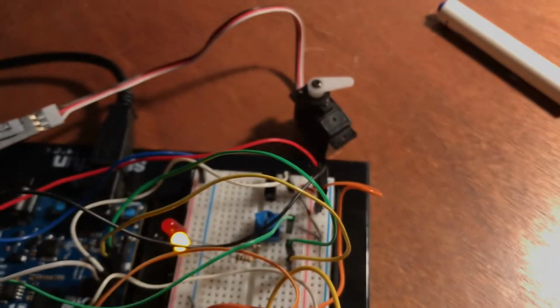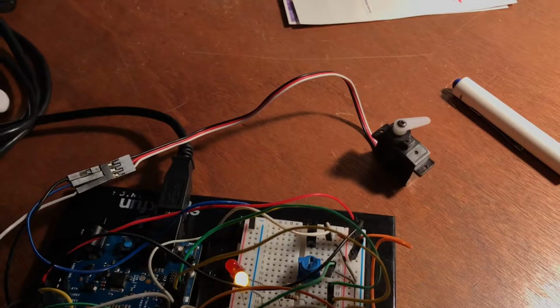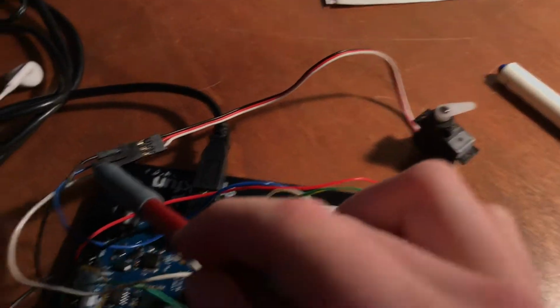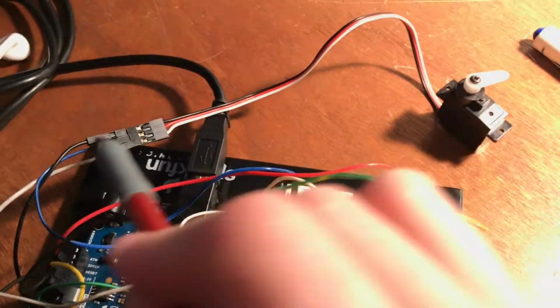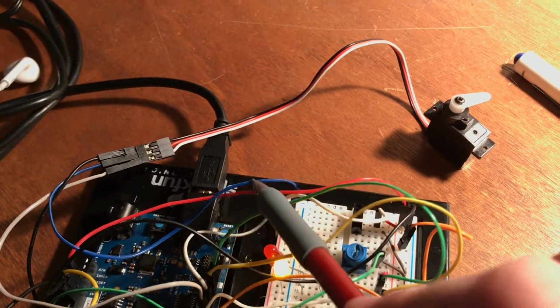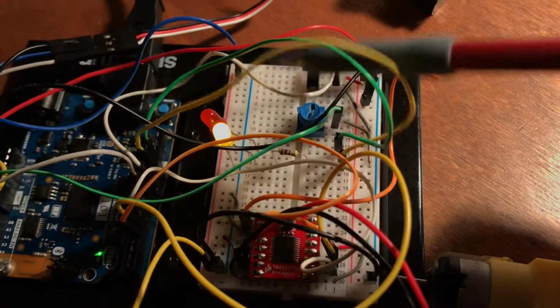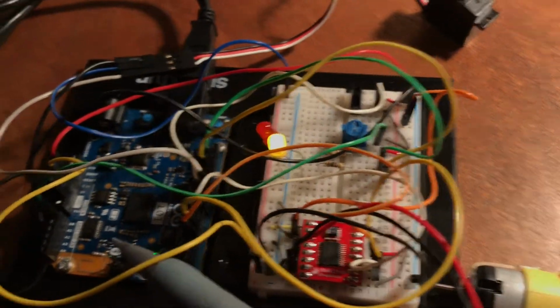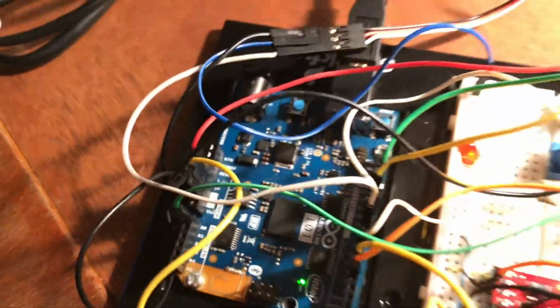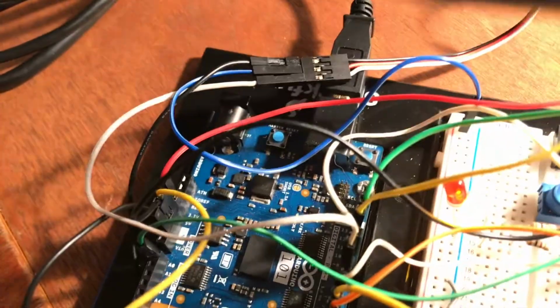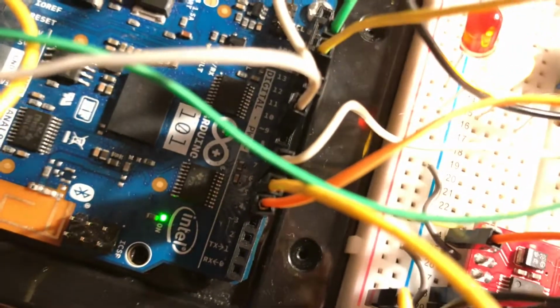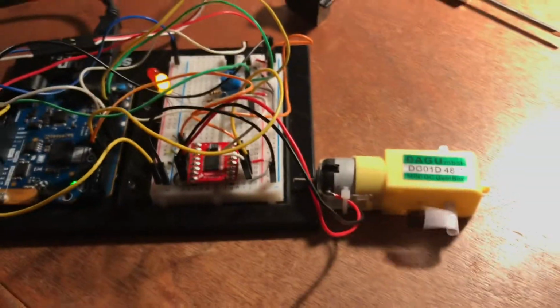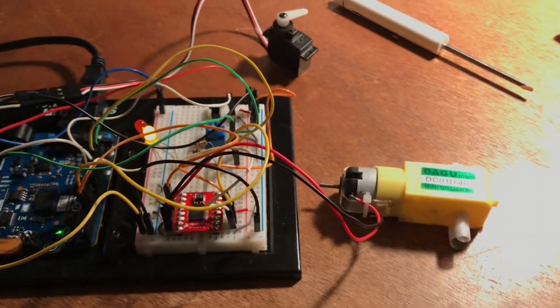And then our servo motor right here: the black wire, which continues through here, is grounding the motor into this ground pin over here. The red wire, which I had to substitute for a blue wire here, is connecting it to 5 volts by connecting to the board here and through this yellow wire that is already connected to the 5 volts. And this white wire connects it to pin number 9 here. So right now we can see that the motor is turning at a slower speed.